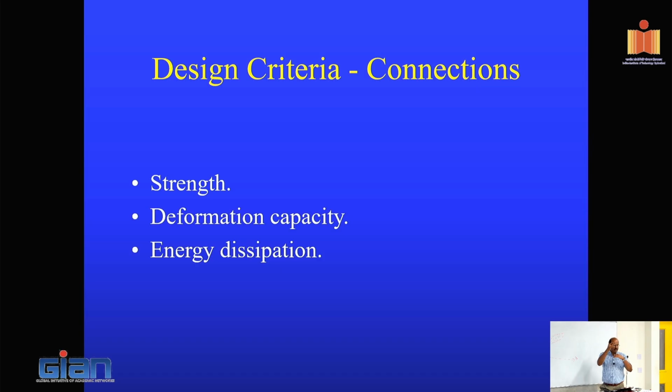The disadvantage is you have to quantify and integrate them so that the structure will have enough energy dissipation capacity and things like that. In cast in place, it kind of came with it, and then we back-calculated and said, okay, it can deform up to 3%. It can provide 30% energy dissipation. Those all came with it because of the way we design.